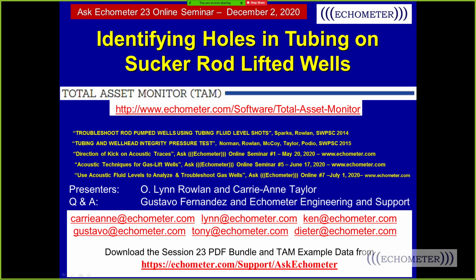But on the paper we talked about on gas wells, there's a presentation that we do during our 5-day school that talks about identifying corrosion in wells when you shoot fluid levels, because you can see excessive corrosion in collars that is like a hole, but it doesn't communicate.